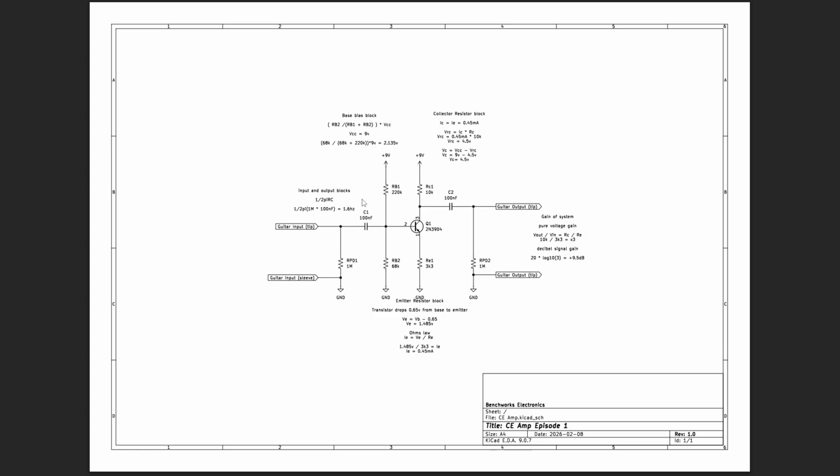And then we've got another capacitor with a resistor, which just makes sure that whatever happened in the middle here in this amplifier, we still end up with everything above 1.6 Hertz and nothing below it, which means that all of this power here stays on the right hand side of this input capacitor and the left hand side of this output capacitor. So anything we plug our amplifier into is going to be safe, and anything we plug into our amplifier is going to be safe, which is great.